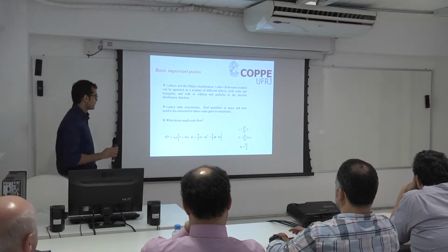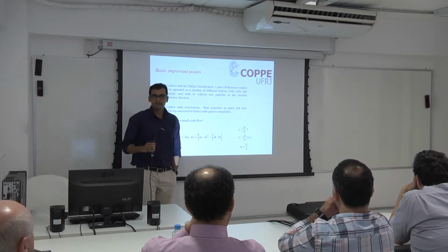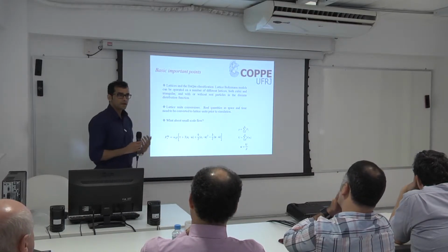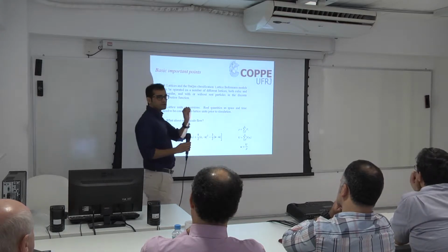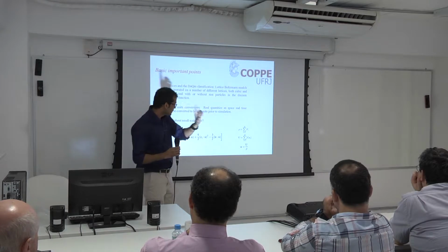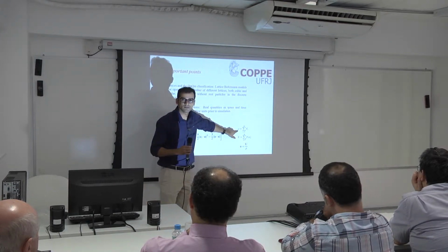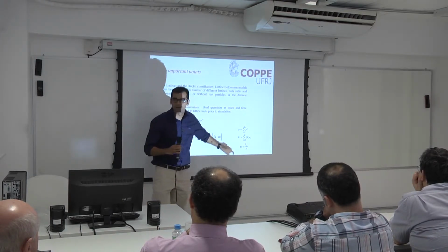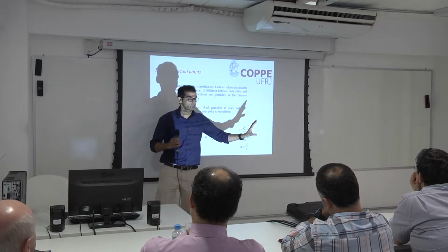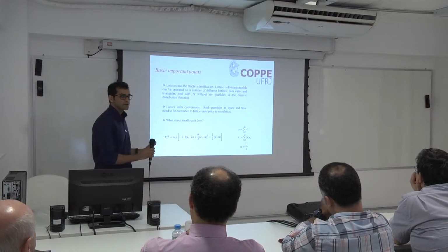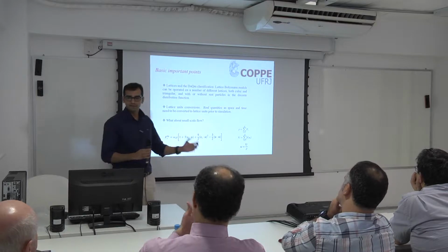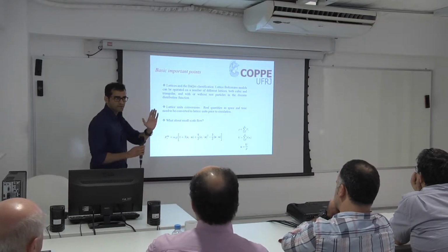Now, when I talk about lattice points and fluid particles, propagation of the distribution function, each lattice point has a certain density value and a certain momentum value. And these density and momentum propagate in the mesh, because in Lattice-Boltzmann, the mesh is propagating itself. That's a key concept. Pay attention to that.